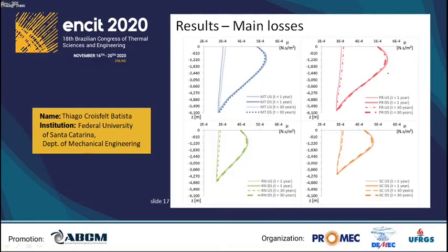Another finding is that the water viscosity cannot be neglected. It varies significantly along the strings. This affects the calculations of the Reynolds number and therefore the estimated friction factor, the Nusselt number, and the heat transfer coefficient. All the hydrodynamic and thermal problems are dependent on the variations in viscosity.